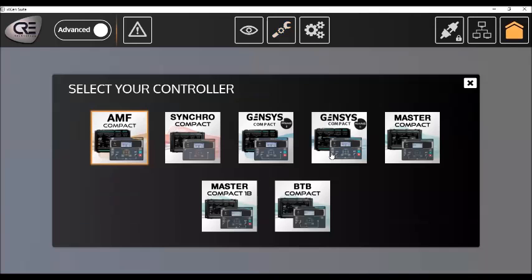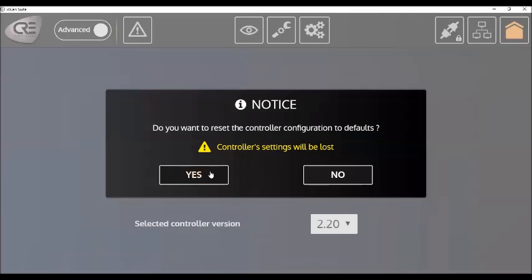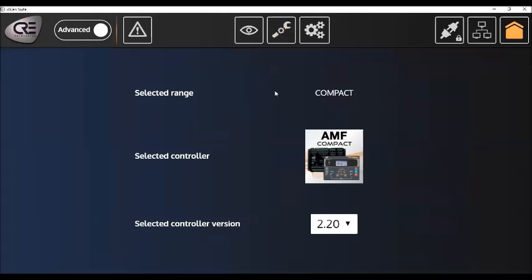So now we go to the hysteresis system. The hysteresis system is to activate the digital output regarding information about two digital inputs, a low and high level, or with an analog input, so with two different thresholds.